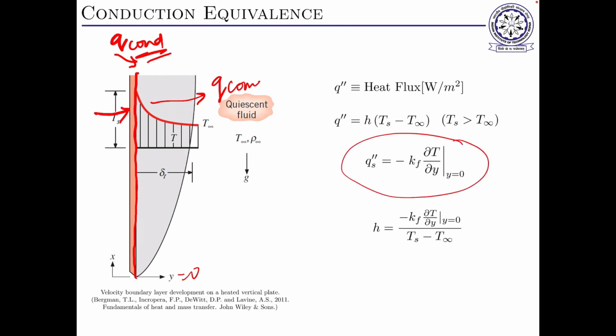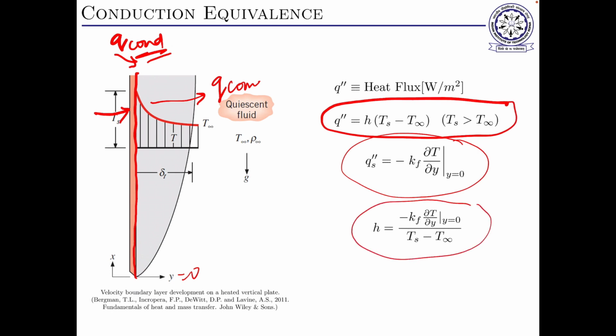This is Fourier's law, and this is Newton's law of cooling. When we equate them, we will get this heat transfer coefficient. What we need can be found from properties or measured by thermocouple. This is the profile of temperature at the surface of the layer or the boundary, that we need to calculate somehow, or we will see.